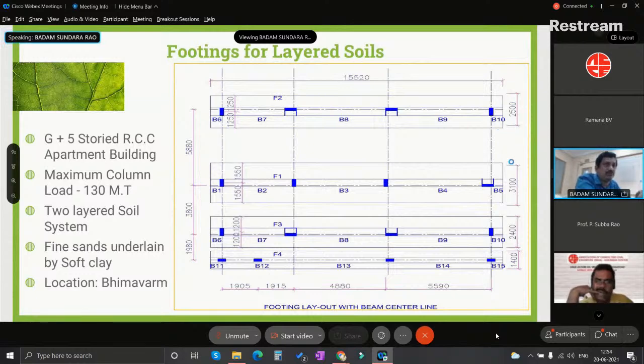With restricting the depth of the foundation, our pressure will not go much beyond the farther depth into the soil. That is our concept of design. Once we restrict the depth of influence, the settlements that we have encountered, we have control over that. Even though they were exceeding, the excess is not beyond too much. That's the concept we have used.